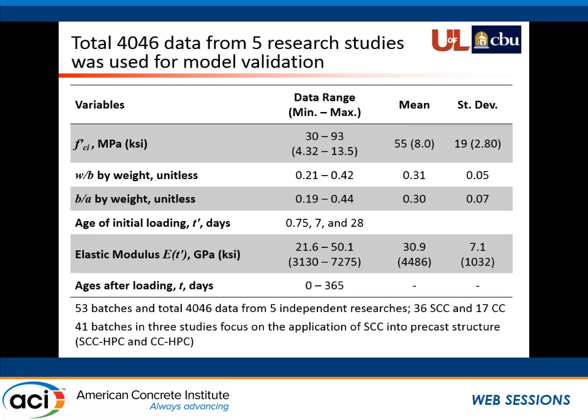The elastic modulus ranges over here, and the age of loading is 0 to 365 days. Not only taking the data at the end of the creep, we try to fit our model to the entire lifetime of the creep deformation. So Dr. Bai will present why the age of loading is quite important in our prediction model.